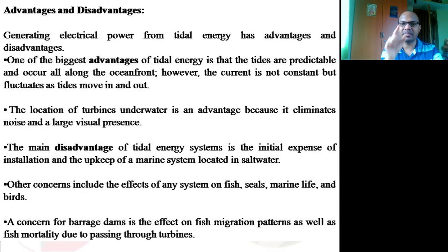It will be separated in a cyclic process. The main disadvantage of this system is that 50% of the potential energy is sacrificed in introducing the variation in the water level of the two basins. Is it clear? In case of off-peak power from the base load plant, the interconnected transmission system is used to pump the water to the high basin for net energy gain.